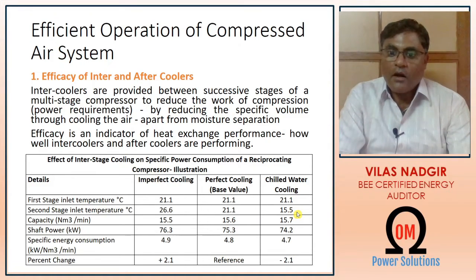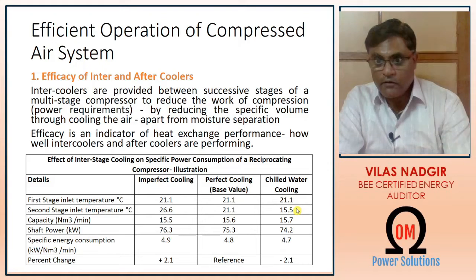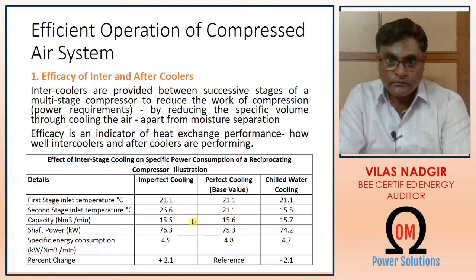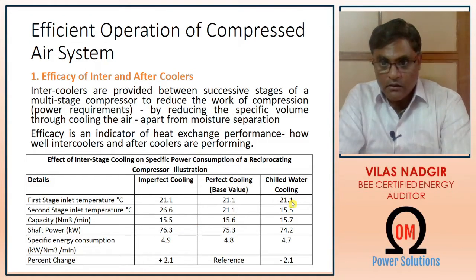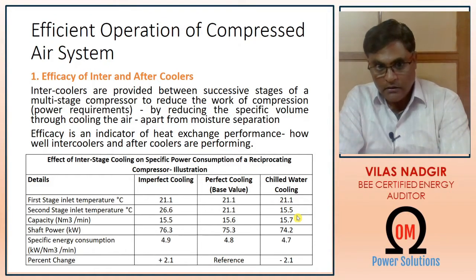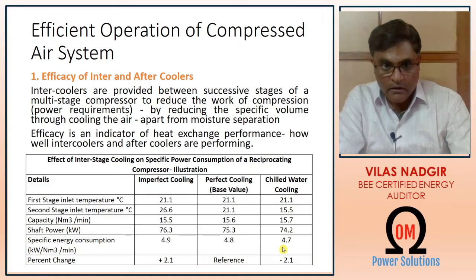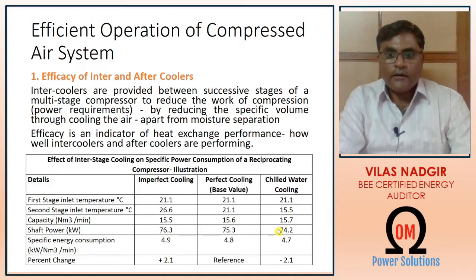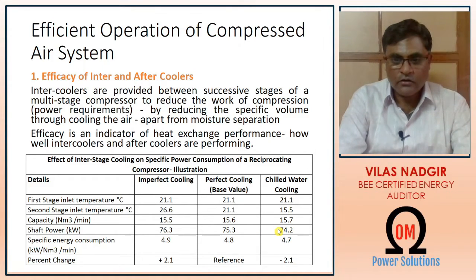Here we have provided very high cooling. When we provide very high cooling, the capacity in cubic meter per minute, that flow rate, increases, and shaft power decreases, specific energy consumption decreases, percentage of change also decreases. So we have to give more cooling to the compressors.